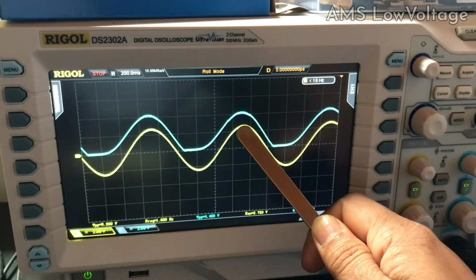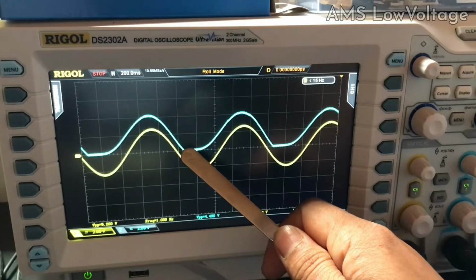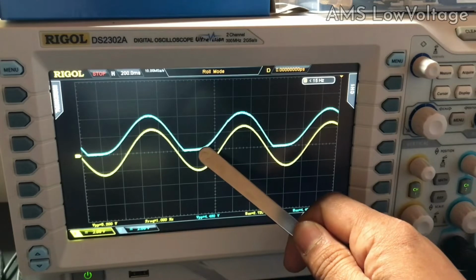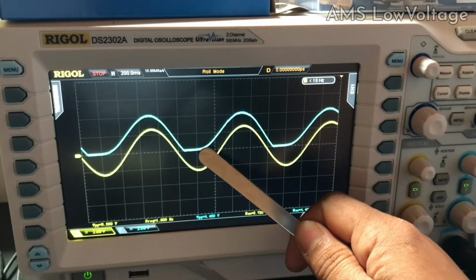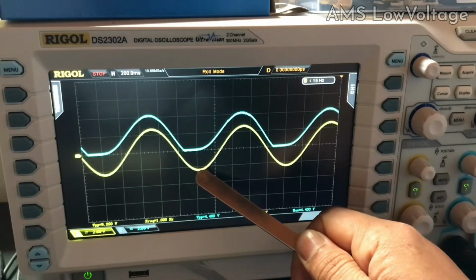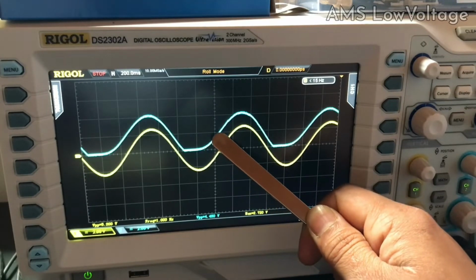But why is the output signal raised up a little bit above the input signal? Because when the capacitor is charged up and the diode is connected as a short to the ground, the capacitor starts charging, and then it stays at 0 voltage. As soon as the input voltage rises from there, the output also starts rising from there.